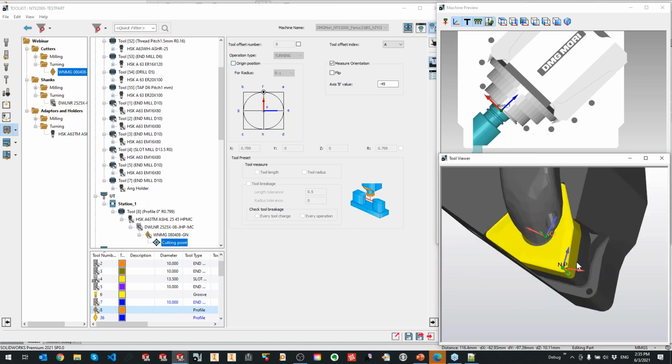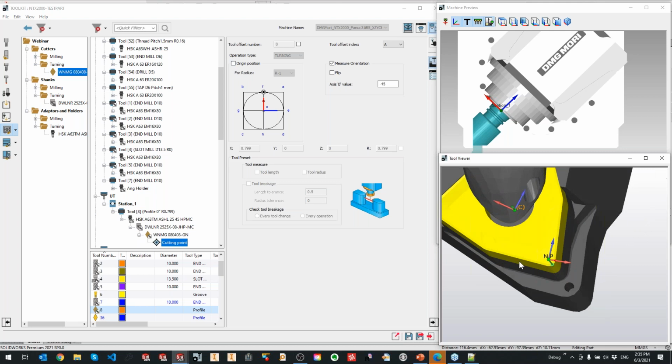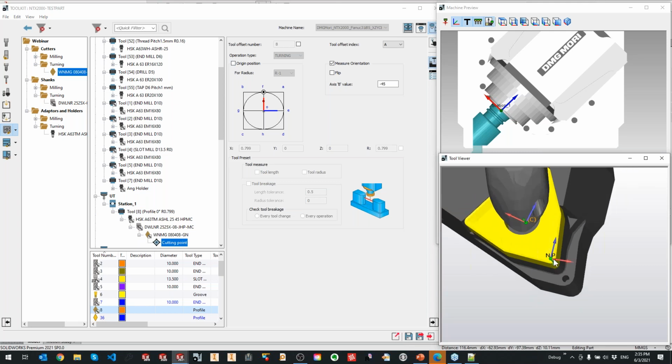And if by default the one that you exported is not automatically selected to the one that you have here, for instance, it can easily happen that it exported over here. In that case, you can use origin position, and everything that is detected by exporting, SolidCAM will show you over here. So you can see that SolidCAM automatically detects more cutting positions.